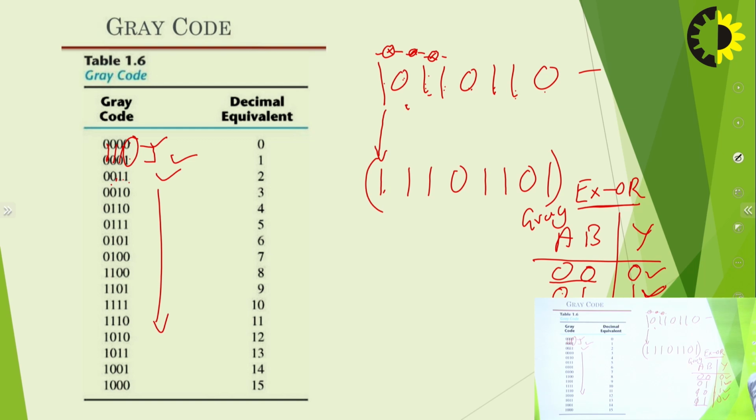So in this way we can convert each binary number into the corresponding gray code. Similarly, if we have the gray code and want to convert it into the corresponding binary number, we can do this also. Let's suppose we have this gray code and we have to convert it to binary. Then the first bit is again the same, and now we perform the XOR between the result and the next bit. So the XOR between 1 and 1, for the same we have 0.